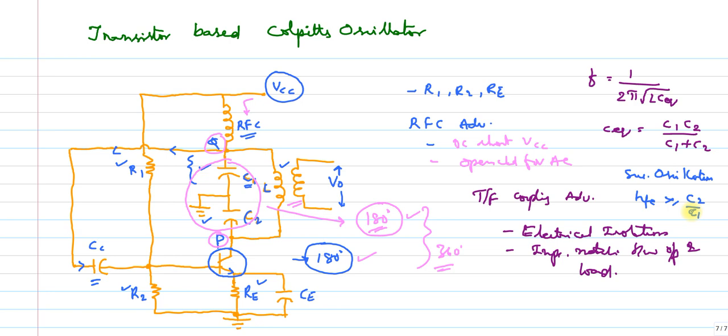So these are the simple points we have to learn from the Colpitts oscillator. You can simply see a common emitter amplifier, and on the collector side we establish this type of oscillator such that two capacitors are split and in parallel with the inductor. And that feedback is given again to the transistor base through the coupling capacitor CC. You can also see the coupling transformer, and you have to know why that coupling transformer is used. So this is the basic concept of the Colpitts oscillator.